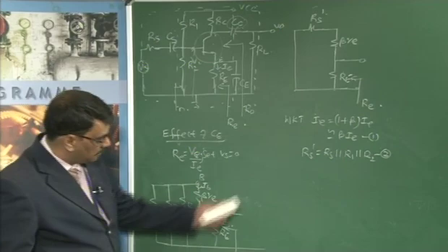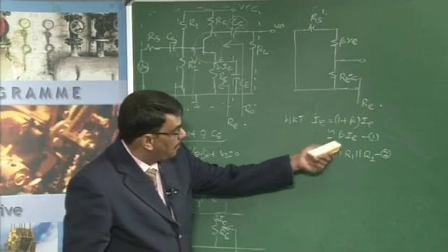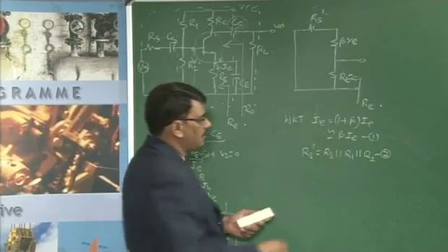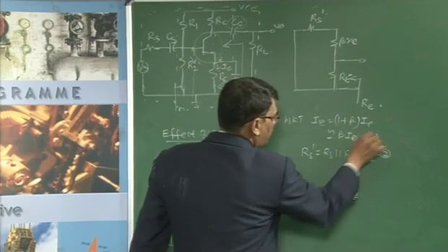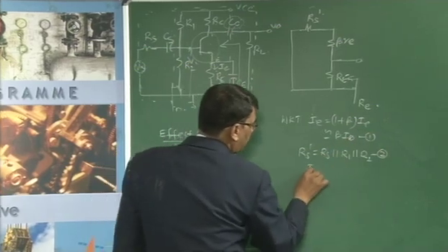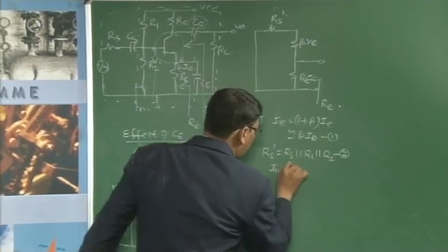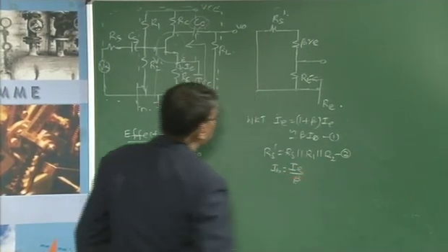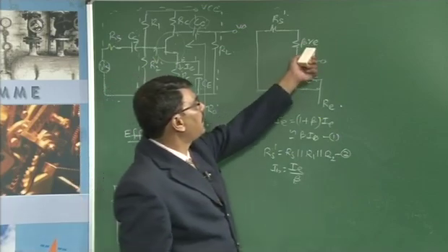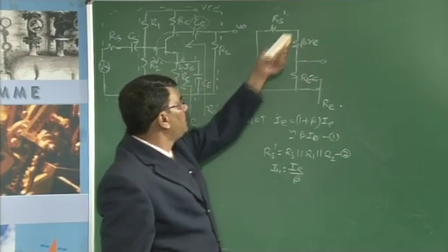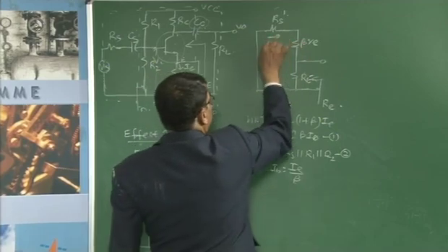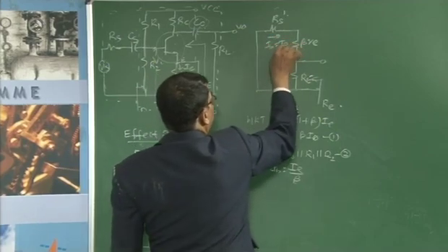Okay. Now, when this is replaced with I_B, from equation 1 you have to replace I_B, which is equal to I_E divided by beta. That means you have to write this in terms of the current I_E. Hence, in this circuit, I_B is equal to I_E by beta.